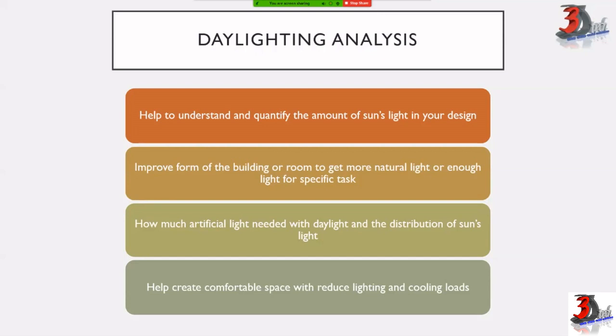Okay. So for daylighting analysis, it is good to do it in the early design process, where daylight feasibility analysis in BIM should be conducted. Okay, so if you conduct this analysis at the beginning of your project, what you can do is avoid glare. You can avoid the penetration of direct sun into certain spaces. Often designers use previous experience and rules of thumb during these early phases. But when you are using BIM, you typically want to study conceptual rooms for their overall shape, aperture layout and size, and general shading strategy.